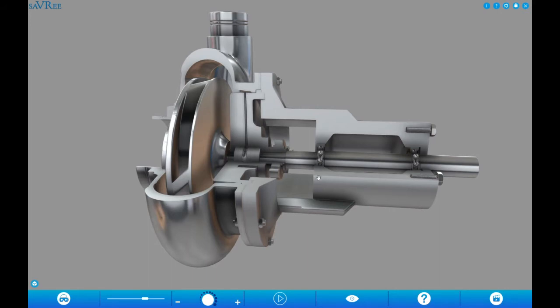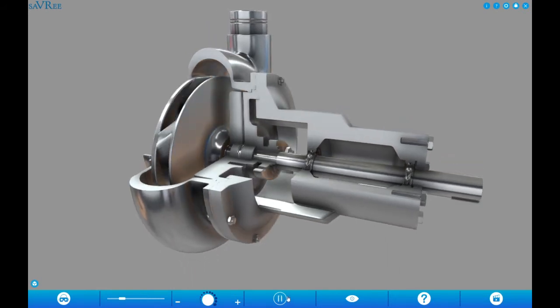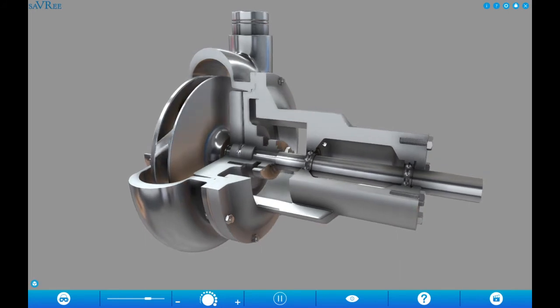The reason to have the bearing is to give non-frictional rotational possibility, and to absorb all possible radial load or radial force which will act on the impeller. So the shaft will be balanced between these two bearings. It will always be in line, and it will help to rotate this impeller with the bare minimum possible friction in the pump. So these two bearings will be required and used for this purpose.